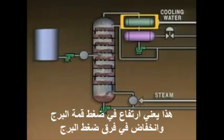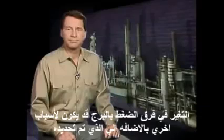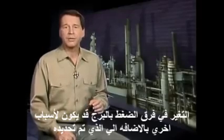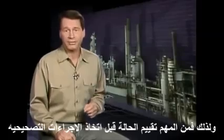This means that the tower top pressure will increase, and the differential pressure will decrease. If a condenser problem is suspected, the condenser should be checked, and corrective action should be taken if necessary. Now, changes in the tower's differential pressure may have other causes in addition to the ones we've identified. So it's important to carefully evaluate any situation before corrective action is taken.